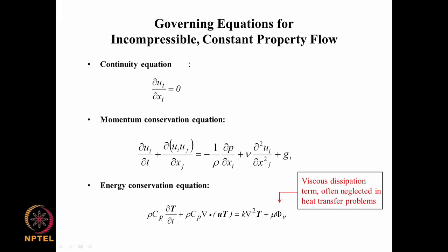is posed in the form of rho Cp, that is specific heat at constant pressure, and therefore in order to get to this particular form we have rewritten the earlier equation which we had written in terms of internal energy, that has been rewritten involving enthalpy. If you do that process, you will get an equation like this.